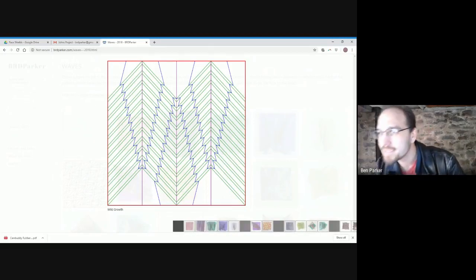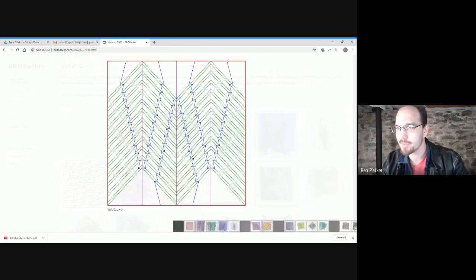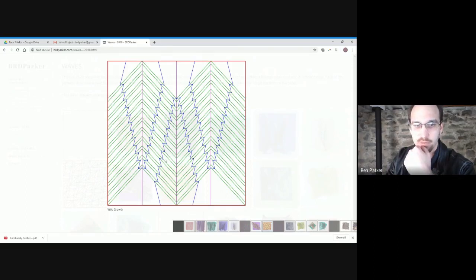And I don't know if you can see it from where you're sitting, but these lines don't actually all connect at a single point. So this all goes back to designing for your material. I'm using paper, and I know that if the laser goes over the same point multiple times, it's going to cut through the paper where I just want to score. So I have to actually backtrack the laser or the lines so they don't all connect. And it's still good enough to get a good connection there. I'll show you how I do that.